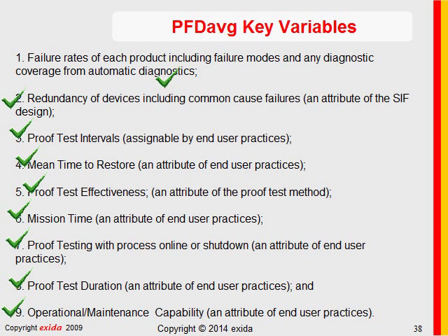If you come up with a better proof test, you may be able to justify a higher proof test coverage, but be careful. I will admit that several end users have come up with some terribly effective proof tests, and Exida has estimated proof test coverages that are better than our FMEDA reports for those specific examples.